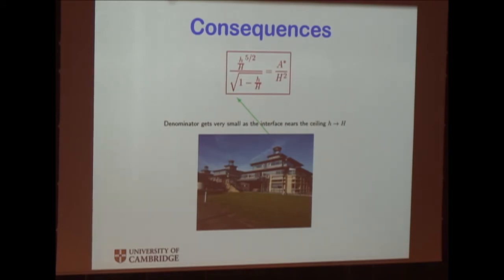layer, and it has a formula like this, where h is the height of the cool lower layer and big H is the height of the room. And you can see that when these become close to 1, when the cool layer gets close to the ceiling, this denominator becomes small, and so you need lots of openable area. And the way you get around this problem is to make an artificially tall space by adding chimneys to make this capital H large. So both of these, this building just embodies both of those very simple principles based on that analysis.